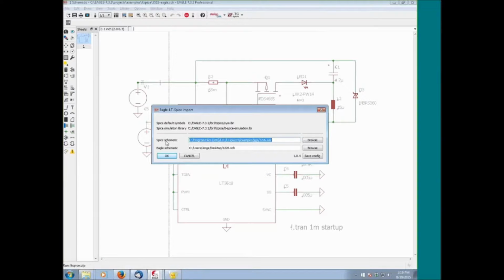That's another issue with the bridge. The ULPs are blocking. As soon as it calls an external program, the ULP will be on hold, waiting for that external program to close before it'll let EAGLE continue to work. So keep that in mind. The call is blocking, something we're looking to improve with ULPs.